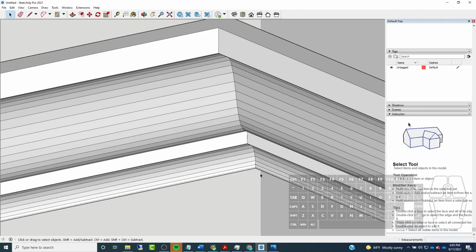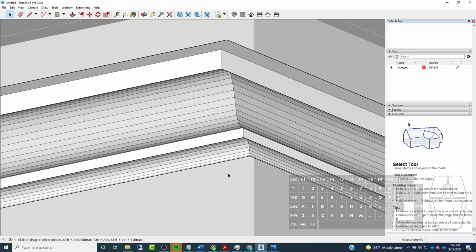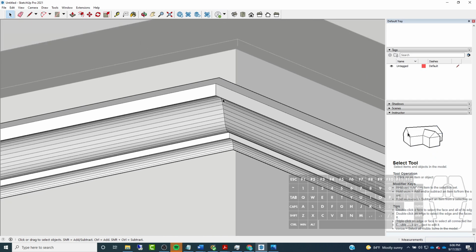If you don't use a spline to make things, it's going to segment it, and it's going to cause all these individual flat segments within the geometry, which when you render that, it's going to be noticeable and it's not going to look great. So within Revit, there was not really a good way to deal with that other than kind of drawing over everything and recreating all of your segmented shapes as splines.